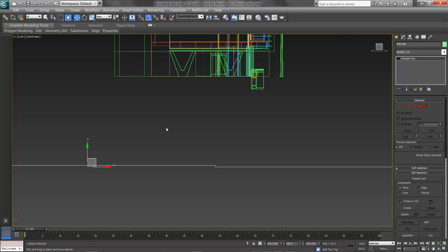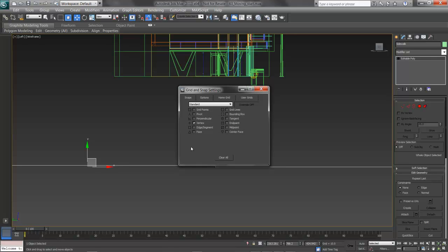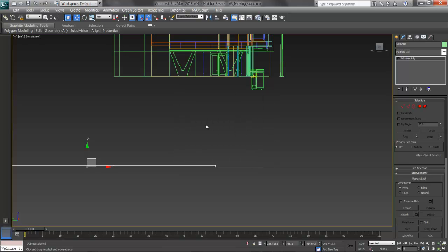We have very powerful snaps available here in 3ds Max. I'll do a little bit of configuration on them. Right-clicking on the 3 with the magnet, my snaps toggle. In here, what I want to do is make sure that grid points is off and vertex is turned on. I'll also go to options and make sure that the snaps use axis constraints. If you'd like to redraw your snap at a different size, there's a display size available. And I like to use a rubber band here, which shows where I went from to where I am. I'll close this dialog and press S for snap.